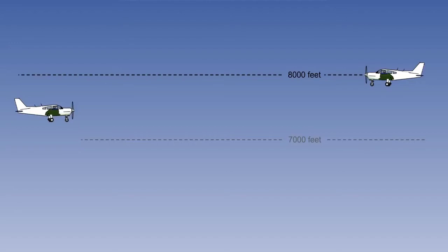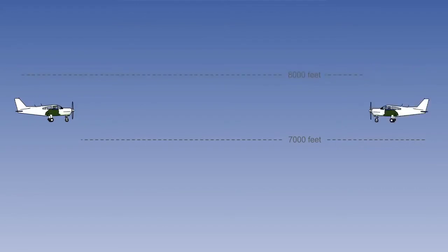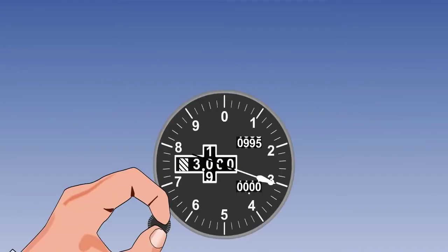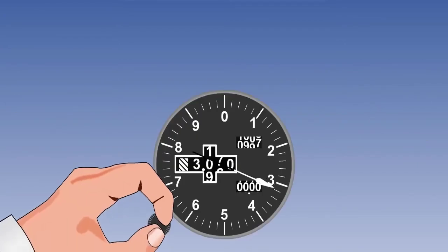And suppose that this other one has corrected for barometric and temperature error at a departure airport, where the sea level pressure and the temperature are higher than when they meet, and has not altered it since. His true altitude will be here. There is a danger of collision unless both aircraft use the same datum pressure, and deal with temperature error the same way. We have a procedure to deal with this.